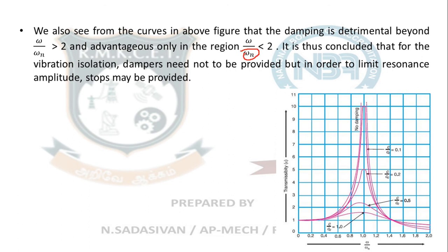Every material has its own characteristic omega n. Now I know the spindle speed of my machine, and I know the magnitude and frequency of the periodic disturbing force. Based on that I choose the machine so that my ratio comes greater than square root of 2, around 1.5 to 2. Such a natural frequency you should have in your machine. That is how you choose your material.